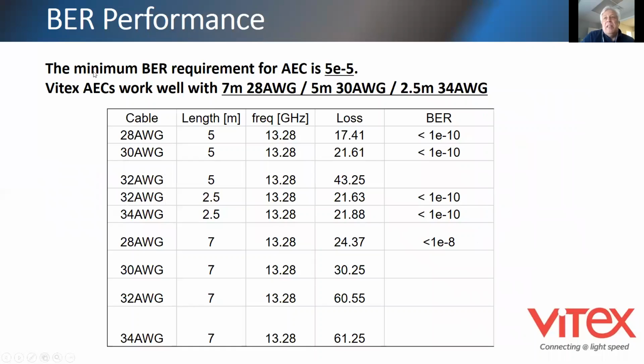Here's just basically showing you some gauges based on the length of your cable. And you can see some of the bit error rates. Those are pre-FEC bit error rates. Post-FEC bit error rates, once again, are 1E minus 15. And some things that aren't mentioned here, but I brought it up in the beginning, is that the latency is 4 nanoseconds, which is pretty good, especially if you're dealing with lots of transitions between going and getting data and returning data.